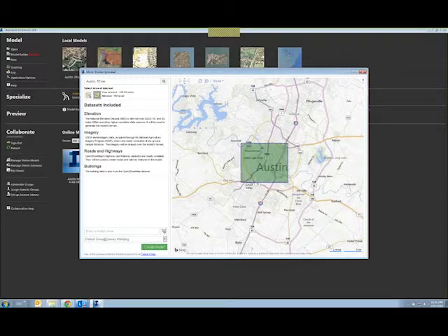With this selected, I simply type in a model name, so we could type in Austin model, and I can create a model. This uses the cloud to go inquire and get data from, again, the national USGS National Elevation Data Set, aerial imagery, as well as OpenStreetMap highway and railway data sets, and then buildings from the OpenStreetMap model.